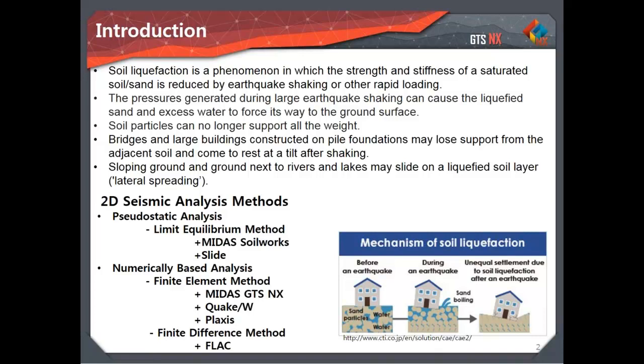There are different methods for studying these kinds of phenomena. Typically for 2D, we have two main options. One is the pseudostatic approach, the most common, a limit equilibrium method analysis of some sort of embankment. For that, we have well-known programs like Slide. MIDAS actually has a 2D conventional software called SoilWorks that can also handle this kind of pseudostatic analysis.